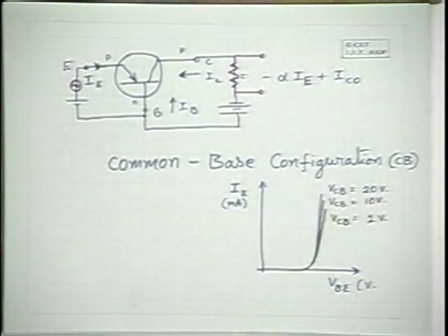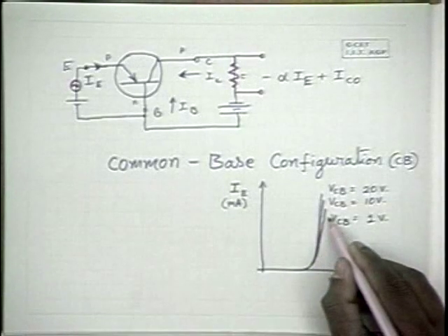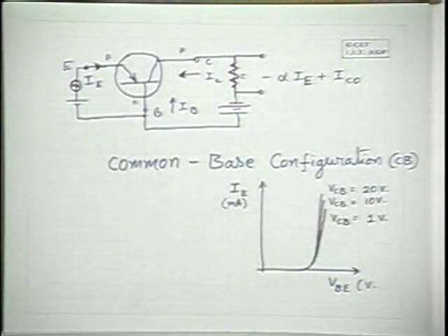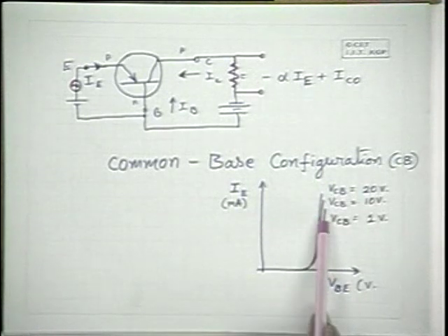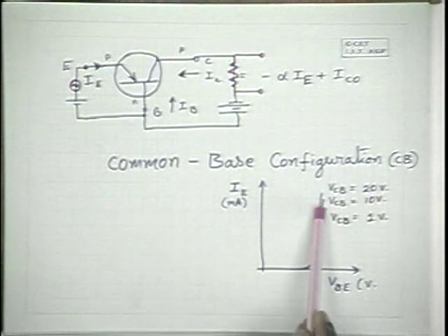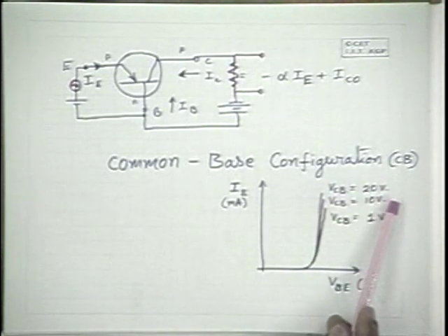An interesting case is when the collector junction is totally open. If the collector is open, it acts like only a PN junction, and the characteristics would be like that of a PN junction diode, in which case the slope will further go down. With open collector, the slope is exactly equal to that of a PN junction diode. So what is responsible for the current to increase with a higher slope when VCB is high?